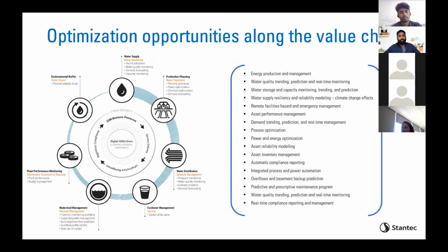The way you do that is by collecting additional information on your equipment and machinery within the wastewater treatment plants, and use that data to look at the patterns in the behaviors of the machinery and come up with a model to predict when a certain equipment can go out of service, things like that. If you can avoid unplanned downtime for any facility, it's going to really help the operators from an efficiency perspective. They can know when to switch one equipment over to the other.